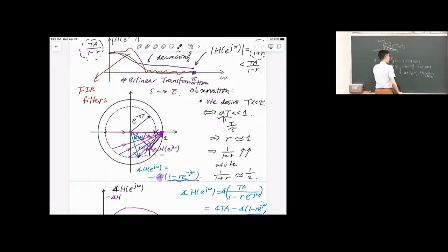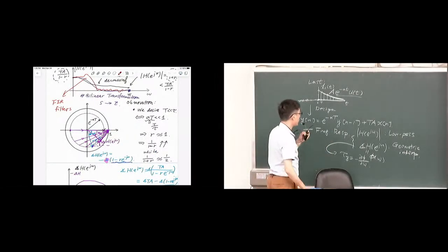And in the end, we briefly introduced the group delay. It turned out that for this phase response, let's say this is phi of omega, the group delay is defined as the negative of the first partial derivative of phi with respect to frequency. You take the first derivative of the phase spectrum with respect to frequency, and you get a delay. So that's a recap of last time.